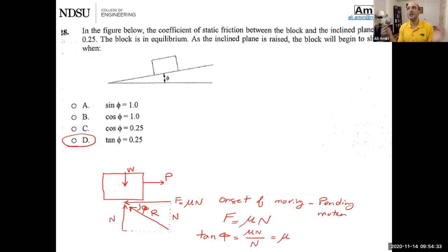So if you know this theory, this is just general friction. If you put any box with any weight on a surface with a friction coefficient of 0.2, or friction coefficient of mu, the angle at which this box starts to slide down is going to be the tangent of that. But let's say you didn't know that. How are you supposed to remember that? So let's just draw the free body diagram here quick. Free body diagram, 3 steps.